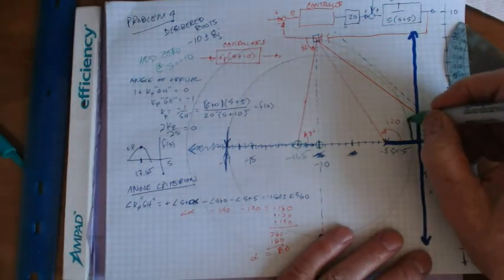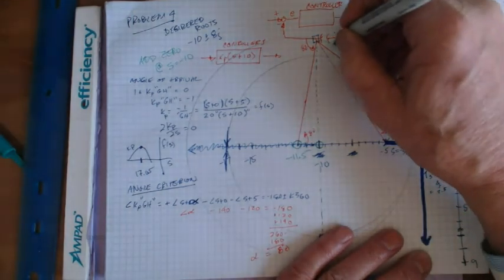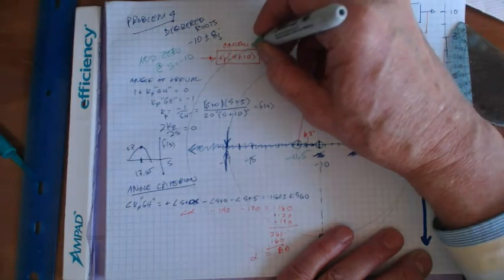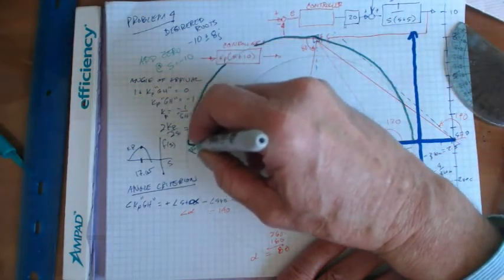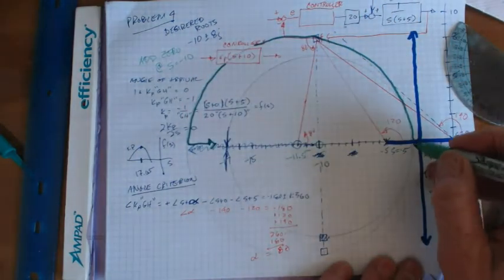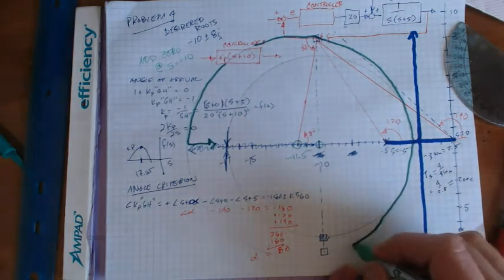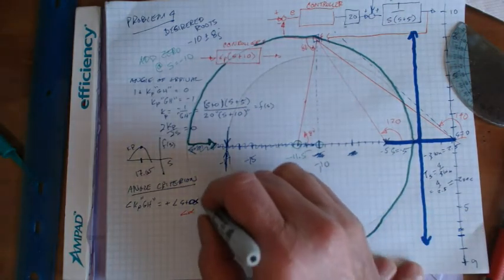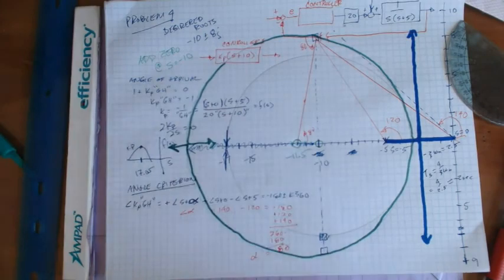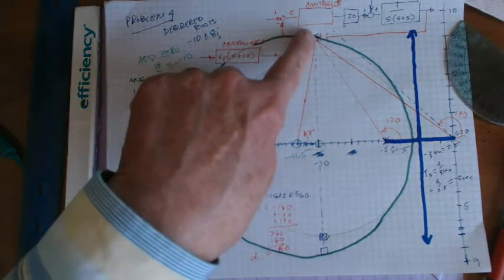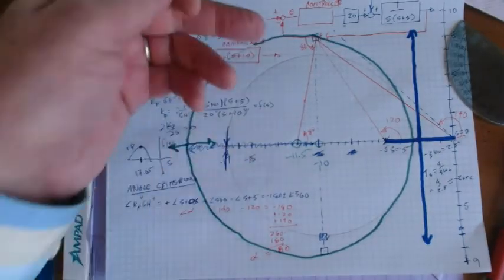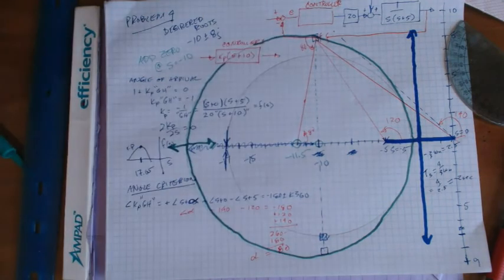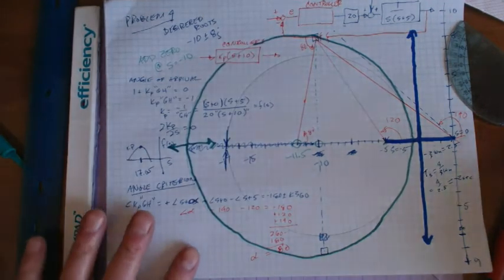So I'll just draw it like this. Boom! Goes right through that spot, right? Isn't that beautiful? And this one goes this way. Here's the other root locus branch. A lot of times you don't even need to do the minus side of it. That goes through the plus, right? And so all we have to do is find out what the gain for that value is. So that's what happens if we added a 0.